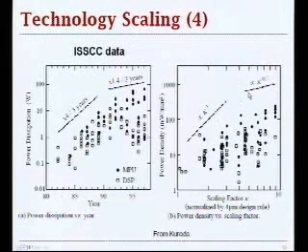There is also another factor that's really important, which is power density. That is the power consumption per unit area: how much power you can dissipate per square millimeter. That ultimately defines your thermal power dissipation, and the capability with which you can take that power out of a chip.